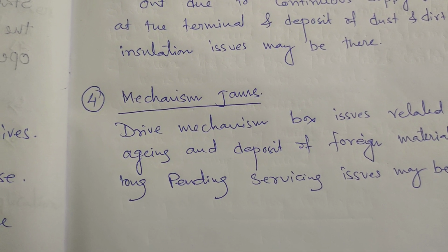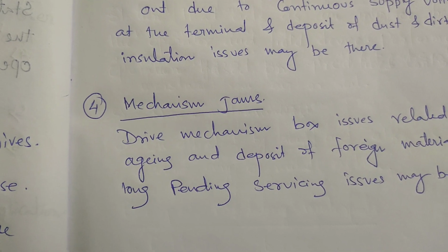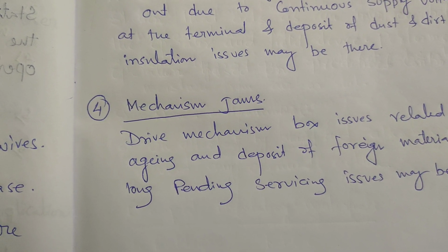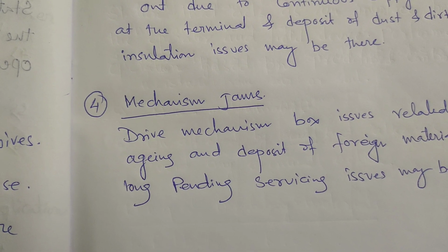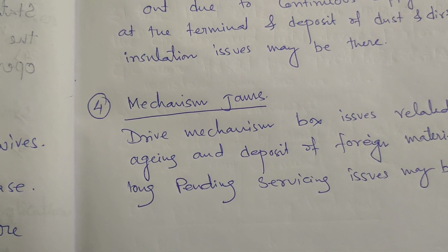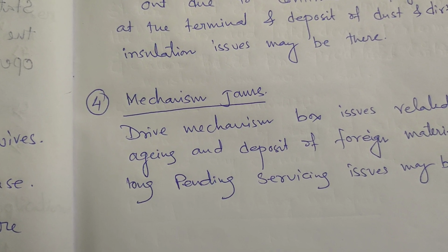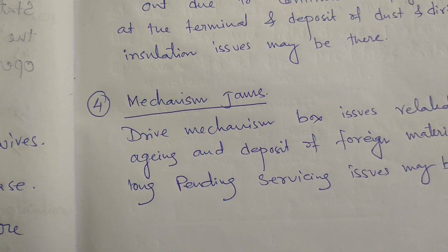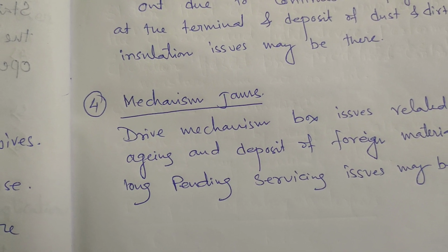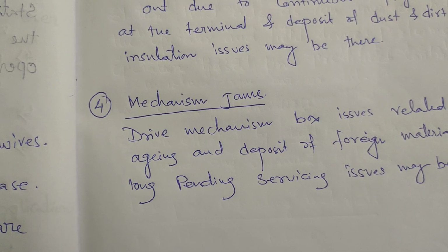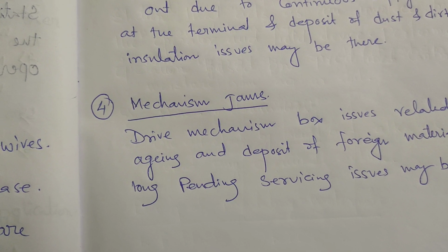If the SF6 density monitor terminal has been cut out and sulfated, then also you cannot operate the circuit breaker close and open functions. It is applicable for a 220 kV circuit breaker. I have experience with it. We could not find the problem, and the whole day we were searching the circuit breaker and the control circuits.